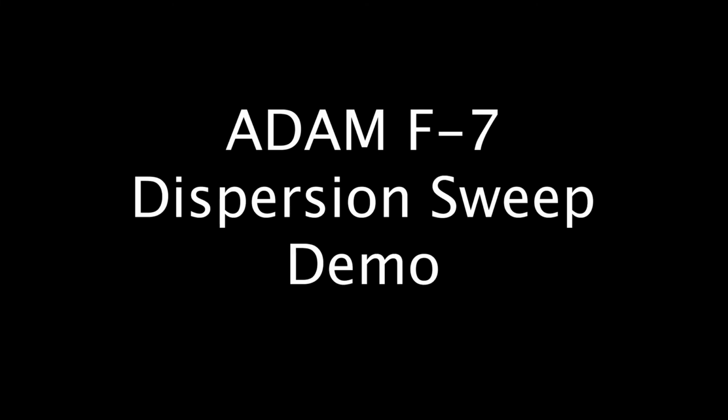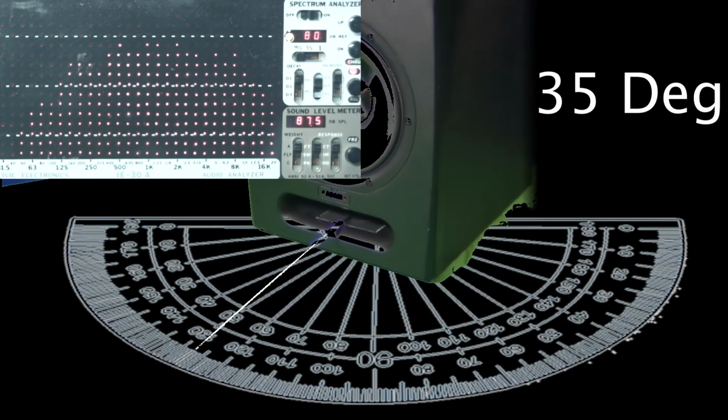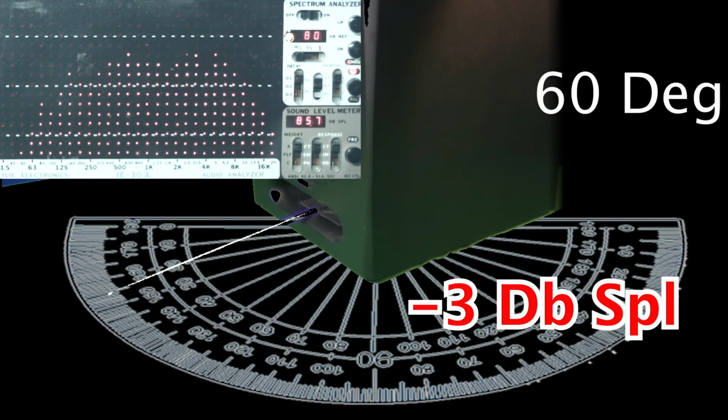The rig uses a Lazy Susan mounted on top of a platform. We then have a reference mic connected to an RTA, or real-time analyzer, or spectrum analyzer, depending on what you want to call it. And you will see an overlay in the form of a protractor on screen. In the top of the screen, you will see the display from the RTA. As we rotate the speaker with the pink noise fed into it, we can see where its output at the microphone begins to fall off.